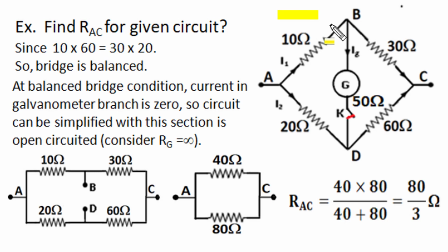In the circuit, 5 resistances are connected among 4 nodes, and we have to find out equivalent resistance across A and C terminal. Now in this configuration, no two resistances are in series or parallel to each other. So series parallel simplification of this circuit is not possible. So in such condition, we can check this circuit for balanced condition of Wheatstone bridge, as we have to find out equivalent resistance across A and C.